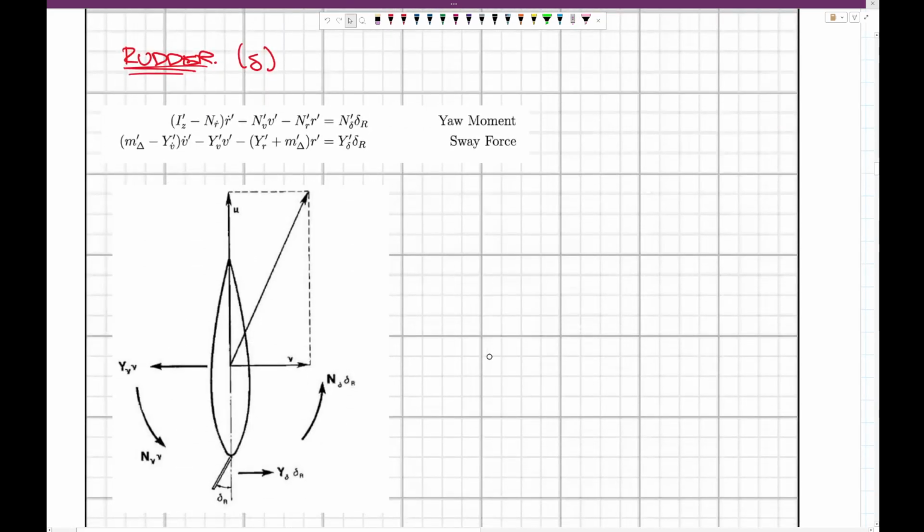So the notation is, if you have a positive rudder angle, so this is a rudder angle, delta is your rudder angle, measured against the longitudinal axis. Positive is going from aft towards port. Right, so this is the back of the boat, so this is the stern, and then this is the port. So moving from the stern to the port is the positive direction of your angle. And naturally, as water comes along here, it's going to force your boat to turn in this direction. So again, N is a moment.